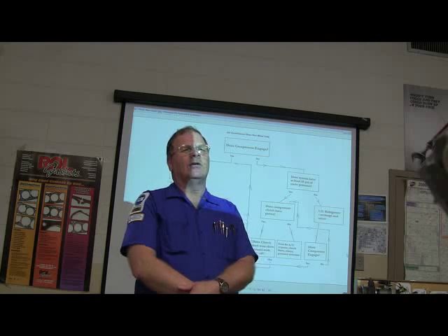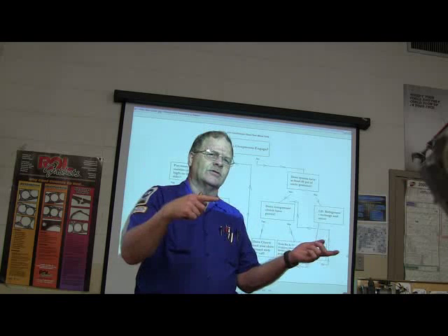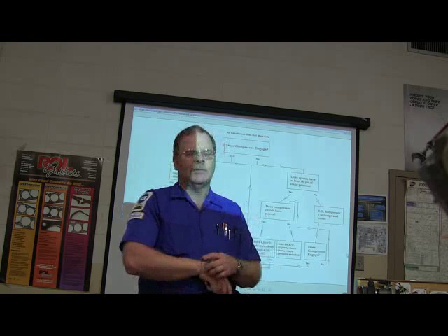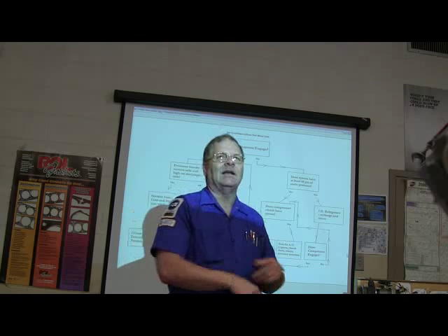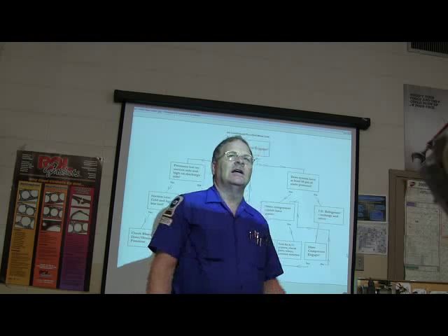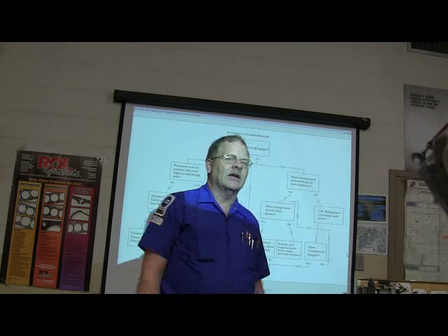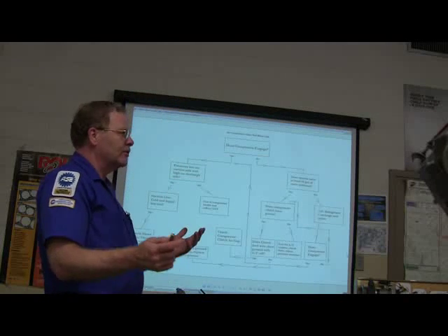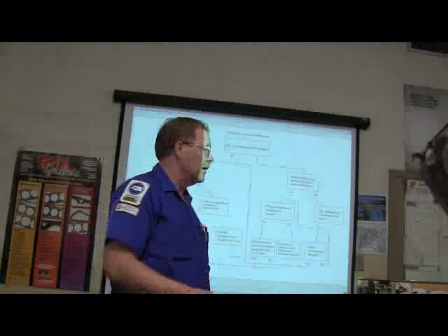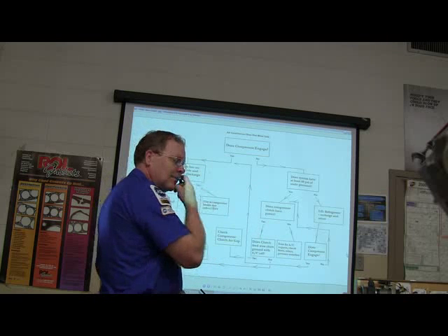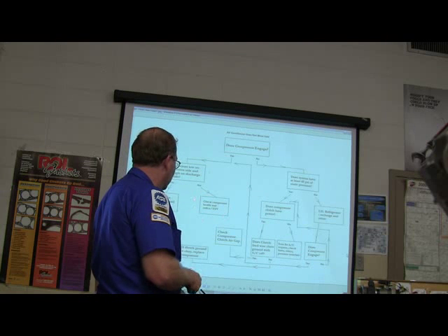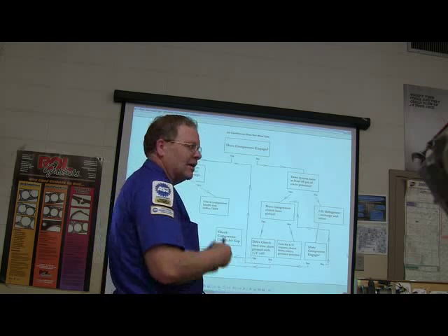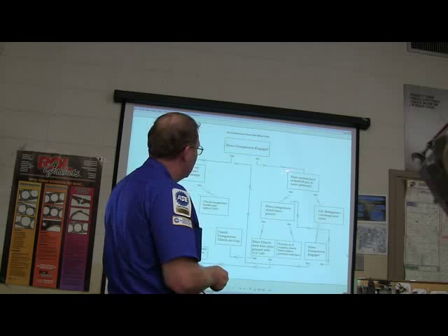One time we had a Toyota in here. It wouldn't cool. Both pressures were low. I said, okay, well, we need to go ahead and put an expansion valve on. So we did that. Nothing changed, and so we backed up and put an evaporator on and took care of it. That was a strange thing. I didn't really understand that. But the proof was in the pudding. When we got through, we had cold air. So we had to put an expansion valve and an evaporator for it to take care of that one. Anyway, there aren't many steps there, but you're going to have to refine what you did.